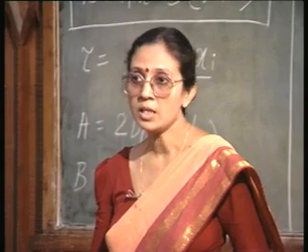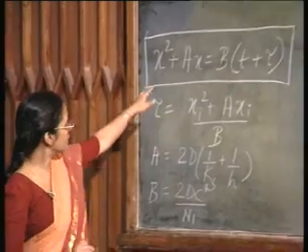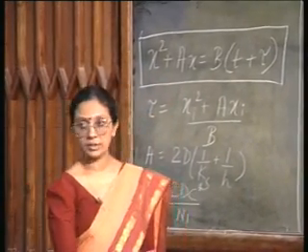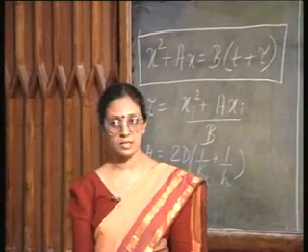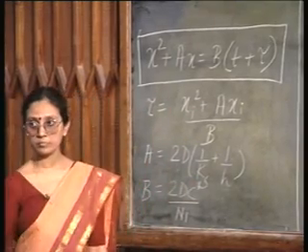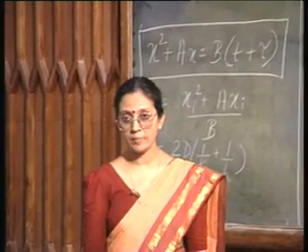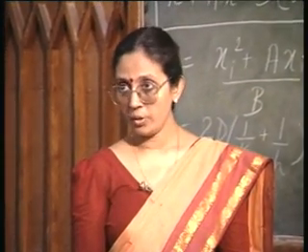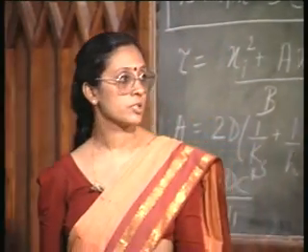So, this is called the linear parabolic rate of oxide growth, and this is the all important equation governing that growth rate, that is x square plus Ax is equal to B into (t plus tau), with A, B and tau having their significance as given here. They are dependent on various constants. So, this is in general the oxidation growth rate.